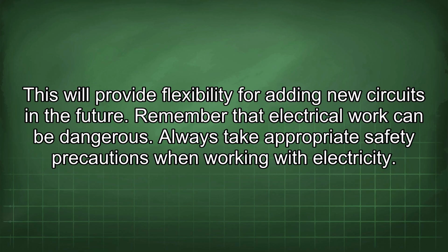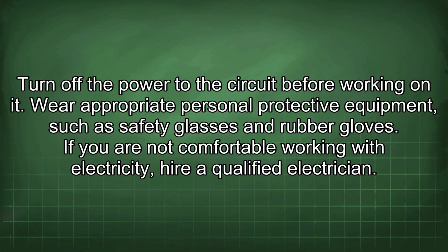Remember that electrical work can be dangerous. Always take appropriate safety precautions when working with electricity. Turn off the power to the circuit before working on it. Wear appropriate personal protective equipment, such as safety glasses and rubber gloves. If you are not comfortable working with electricity, hire a qualified electrician.